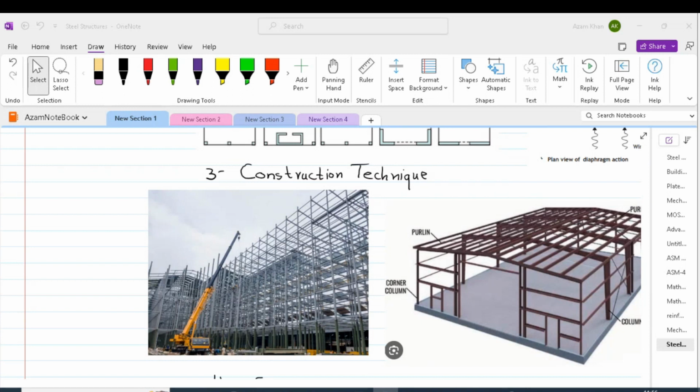After erection of the steel frame, bracing and temporary supports can be installed. After that, floor and roof deck installation will take place. Subsequently, tertiary elements like studs and joists would be installed. After this, fireproofing, coating, and mechanical and electrical systems would be installed. Finally, interior and exterior finishes would be installed and exterior cladding would be placed. So this is the normal construction sequence of steel buildings.